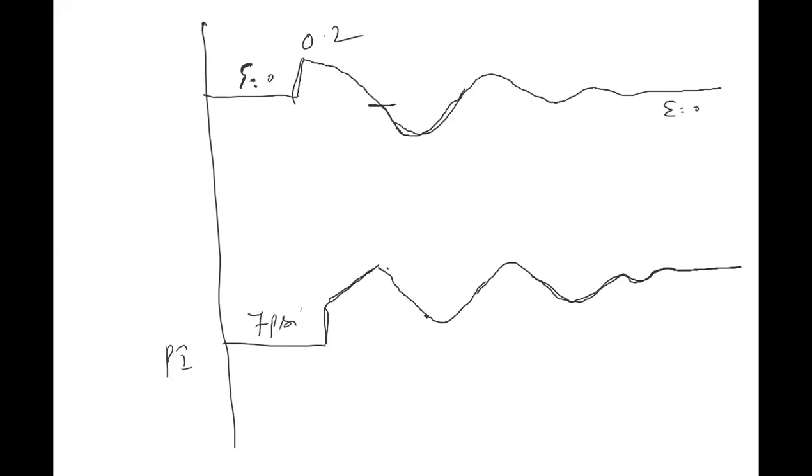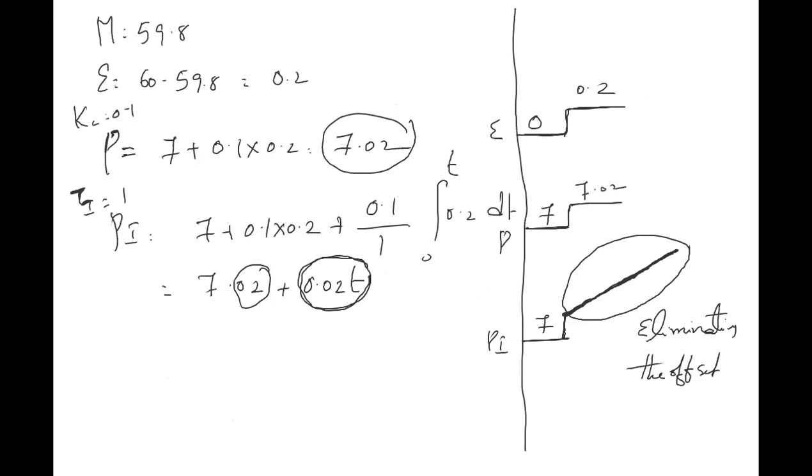Imagine that, don't look at these graphs, just follow my explanation. Assume that you are working as a proportional integral controller. When you see a CSTR temperature of 59.8, you put your hand on the control valve and slowly close it. When you are slowly closing, you cannot stop exactly at 60, because there will be some time lag. You are changing the cooling water, but it doesn't reflect immediately on the temperature. By the time it reflects, you might have moved the control valve a little more, because the output increases as a function of time, which means you are continuously moving the valve.